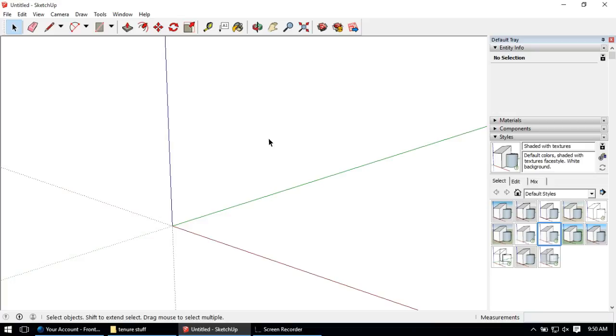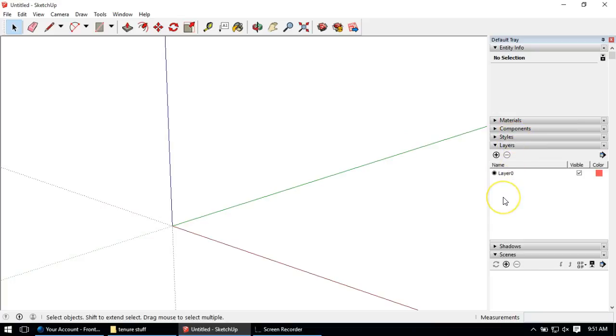Now, one thing the directions talks about is layers. I am not going to have you do layers like this. This is not a good way to do layers in SketchUp. Layers do work a lot like AutoCAD's, as the instruction implies, but we haven't really taught you things in this class about blocks in AutoCAD. And so I'll just simply say you should. We're going to be using groups in SketchUp, and groups are a lot like blocks, so you should follow the rules of blocks. Now, we haven't taught you what that means, so I'm not going to go into the detail, but what that does mean, I'm going to tell you now, is you always make a block on layer 0, and in SketchUp, most all of the time, you always make all your objects groups, and you want your groups to be on layer 0, so we are going to work on layer 0.